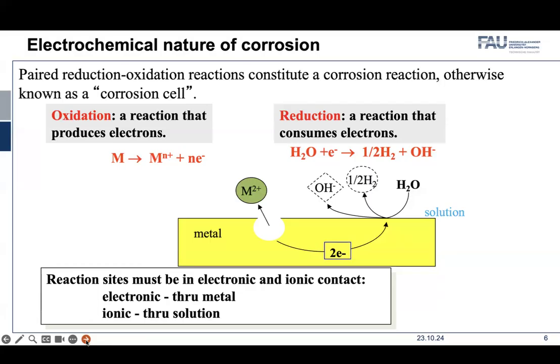There is no specific site becoming attacked. And then a pure metal without any heterogeneities, if you make a single crystal of magnesium, there's no defect. You have eliminated all defects. This is very hypothetical. If that is the case, then it will corrode uniformly, because on the whole, the net effect which you can observe macroscopically, it will be uniformly dissolving.